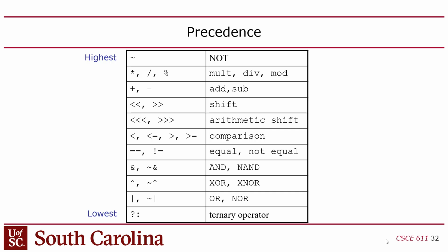They don't because in those languages, the choice between an arithmetic or a logical shift is defined by the type of the value being shifted, whether it's declared as being signed or unsigned. So if you shift an unsigned int, it'll be a logical shift. If you shift a signed int, it'll be an arithmetic shift. But in Verilog, you often just have logical values that don't have a sign in the data type. But there's exceptions to that too, which I'll get to in a minute. But so they have this arithmetic shift. You'll also notice that there is a, oh, it's not in here.